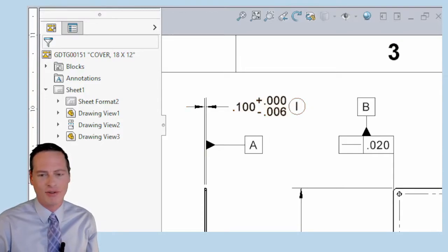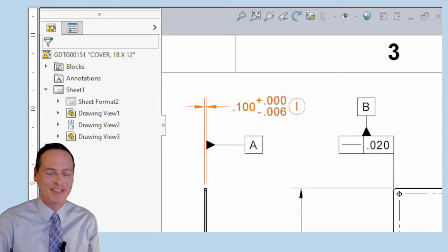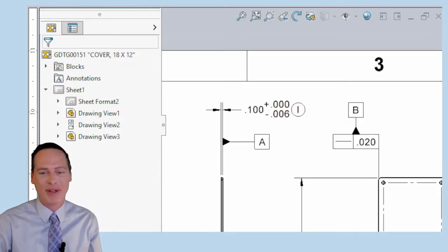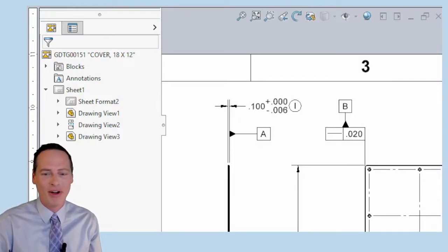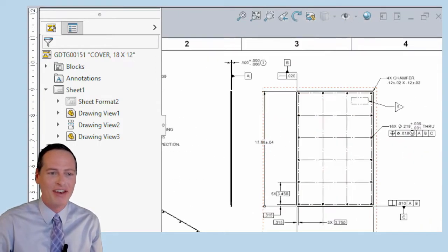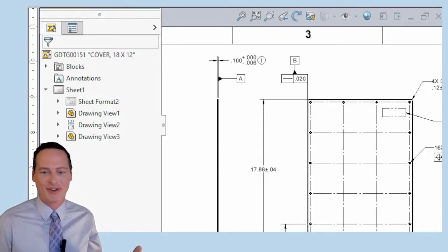There might be some GD&T pros out there who think I should take a couple more steps here to define this material and the thickness and everything. You're probably right, okay? But just to speed through, this is the way I'm going to do it, to keep it a little bit simple for these examples. So I'm calling one side a datum A feature. And so here's what I mean by this being a really traditional kind of datum reference frame. This is the way a lot of people are taught. I think that the standard really relies on this quite a bit in the illustrations.